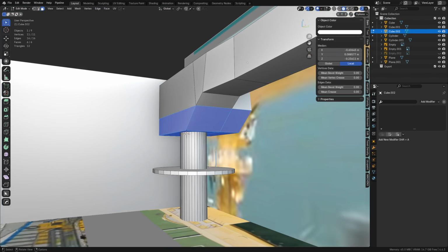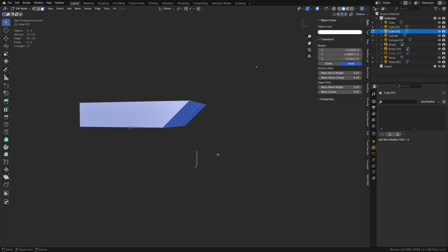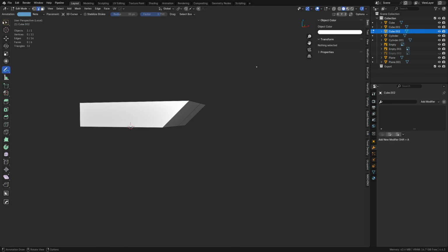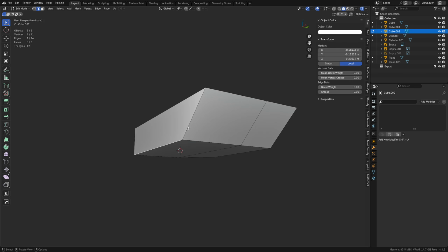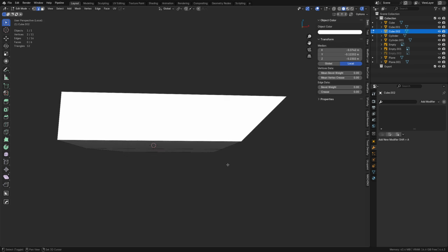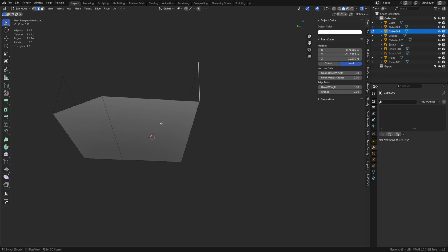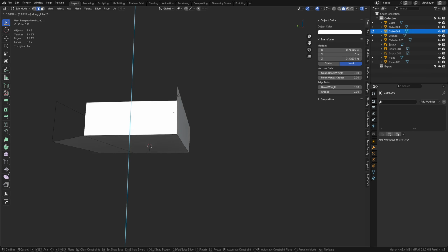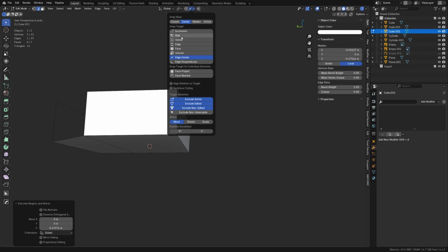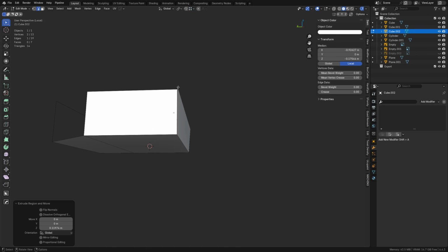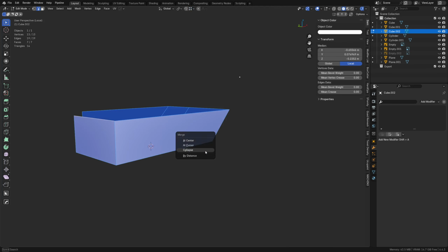We could take this and detail it, right? I'm going to separate it as a new object. We can isolate it for just a moment. Get rid of some of those annotations real quick. There you go. And now the backside's going to be rounded. So I want to go ahead and do this vertex snap now. Not center, closest. Boom. Merge by distance. We can symmetrize this up if needed later.